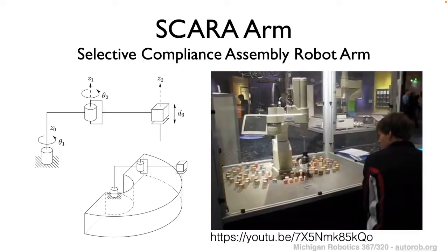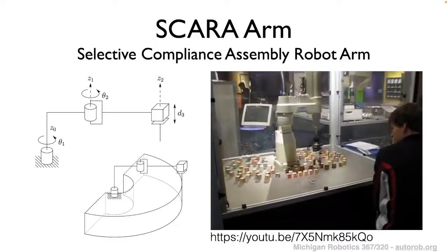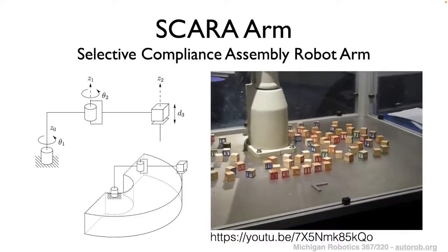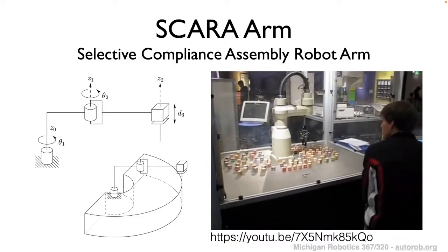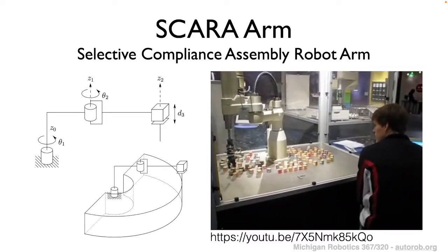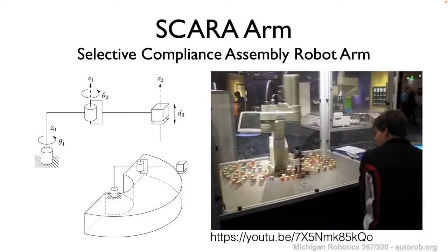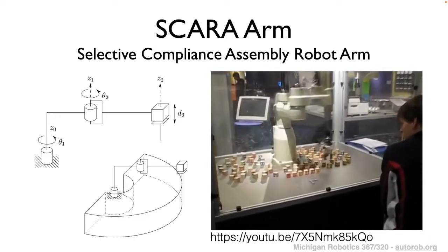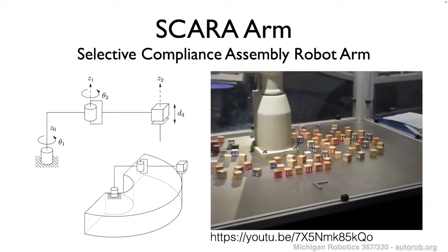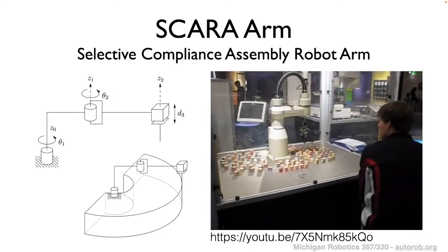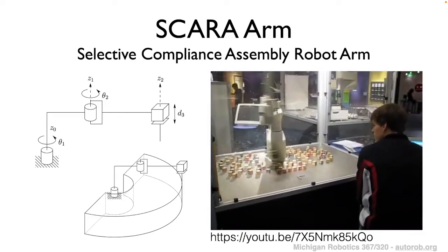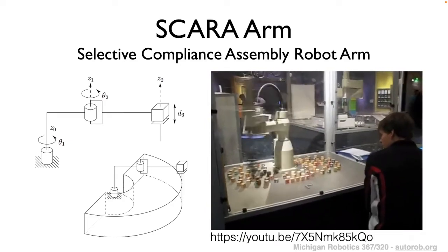And so one physical example of a two-link arm that we talked about was the SCARA arm. And so with the exception of an added prismatic end effector, this is an example of a real robotic system that is really based on this two-link pendulum structure, where there are two revolute joints, so one connecting the robot to the base, and then another at that elbow joint that allows the robot arm to rotate about its workspace.